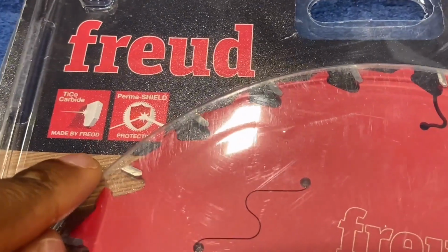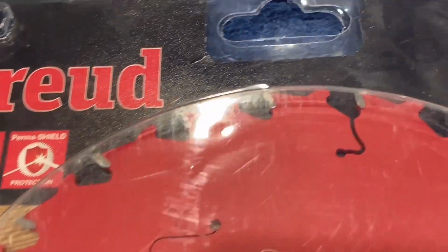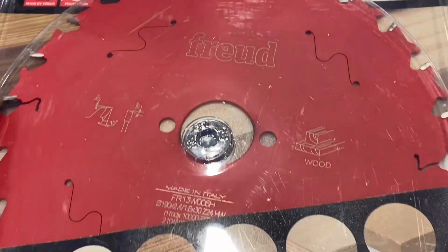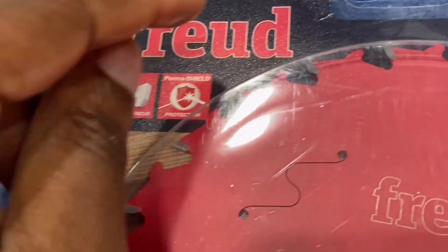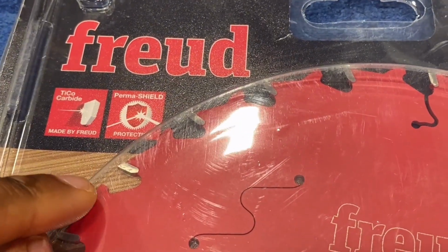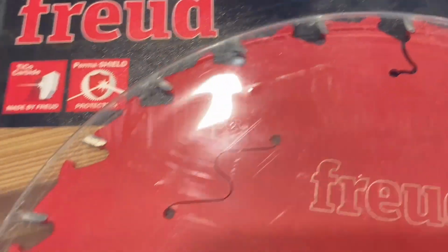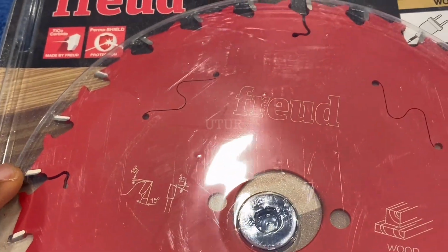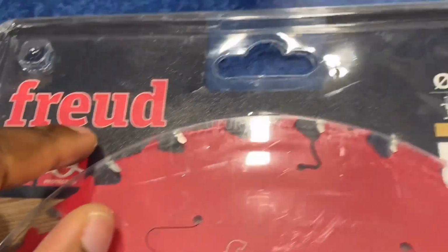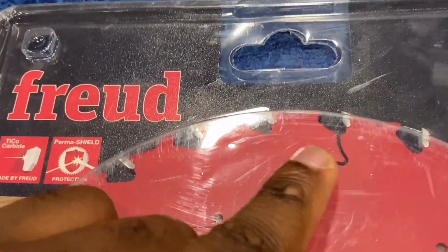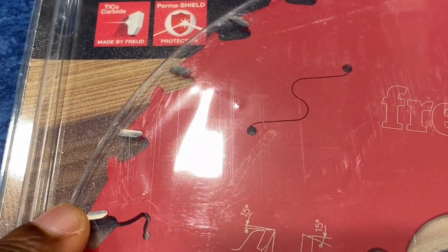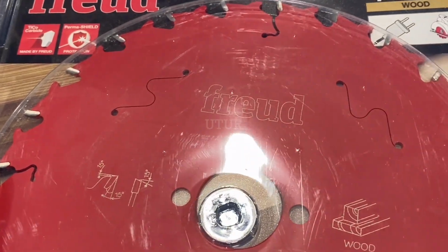The blade teeth are made up of titanium carbide, which is extremely harder than your tungsten carbide. They tend to provide fast, no chip and perfect cuts. This blade is particularly suited for cutting along and across the grain of woods. The positive hook angle essentially means a faster feed and more pull on the blade, as opposed to a negative hook angle, which prevents climbing of the wood or self-feeding of the wood.